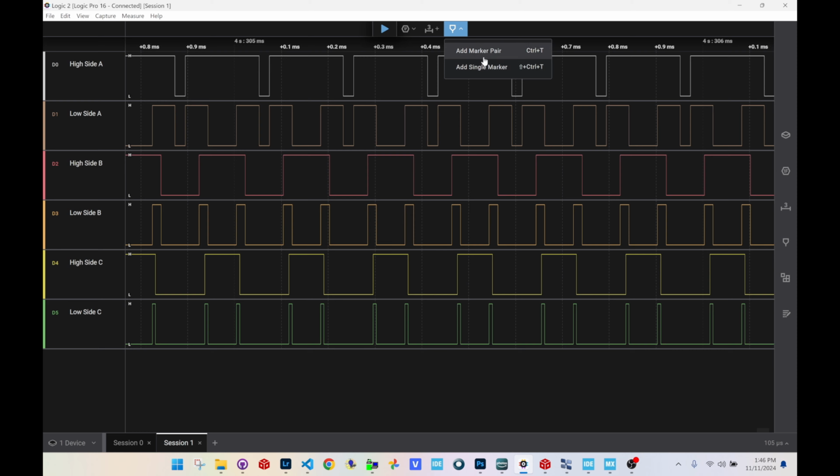Usually you want this PWM frequency to be as high as possible. If it's low, then you'll be able to audibly hear the switching noise. Unfortunately, this motor driver board doesn't support high frequencies, so I have to have the frequency quite low. This is because there's a lot of capacitance on the lines and the motor driver board is pretty cheap. Right now the PWM is running at a frequency of 5 kHz.